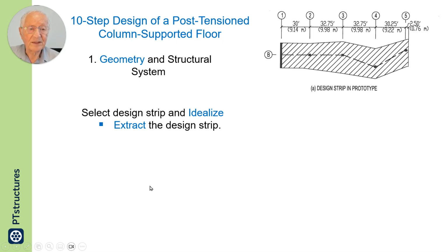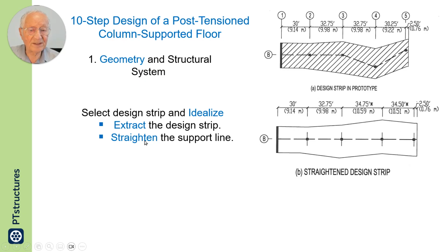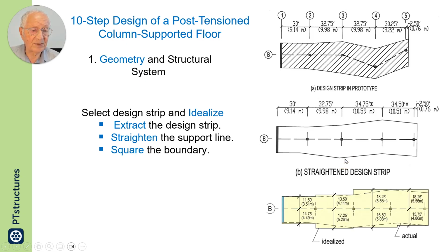We continue with the design by extracting and looking at the design strips one by one. In this case, I have selected one of the design strips. Select design strip and idealize it. Extract the design strip as I have shown here. Straighten the support lines. The support lines are like this, but we straighten the support lines.